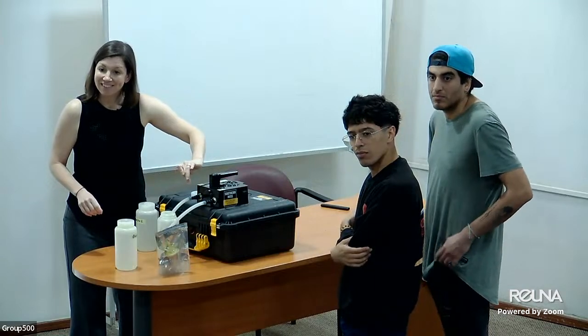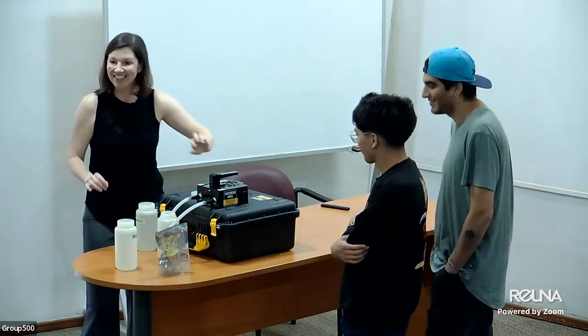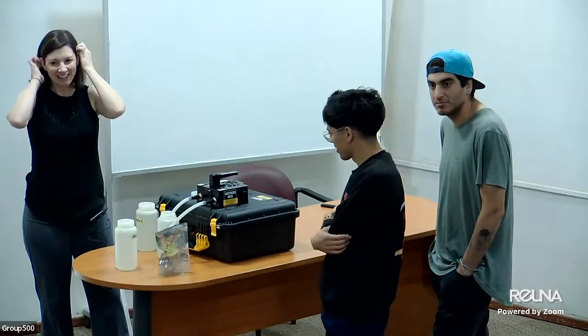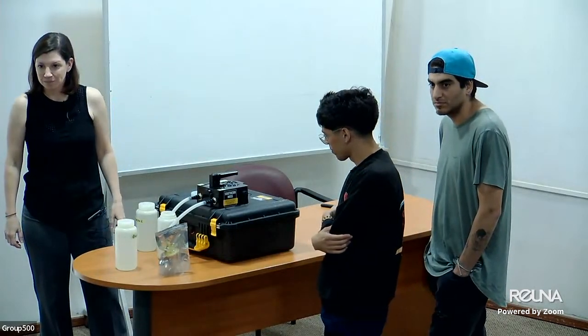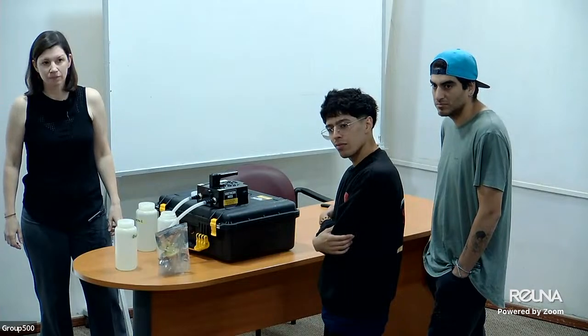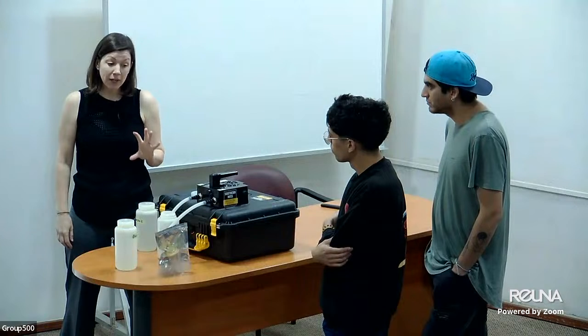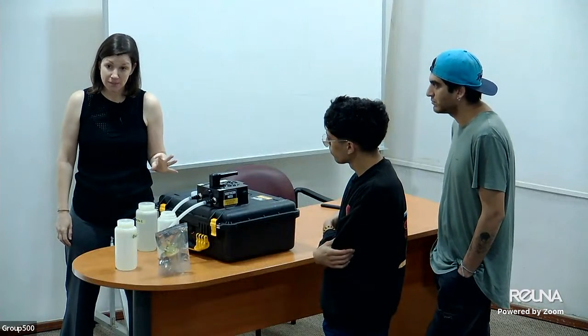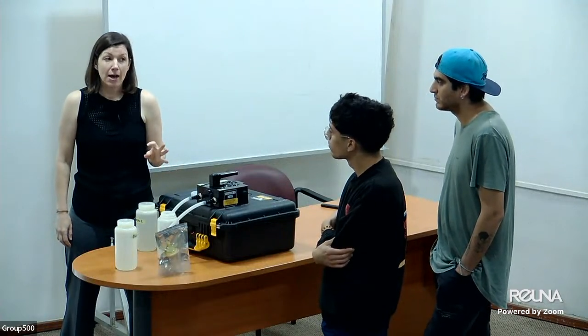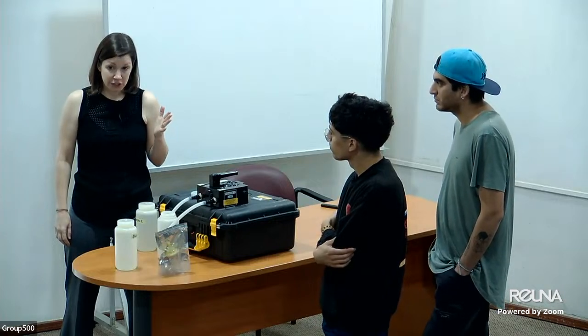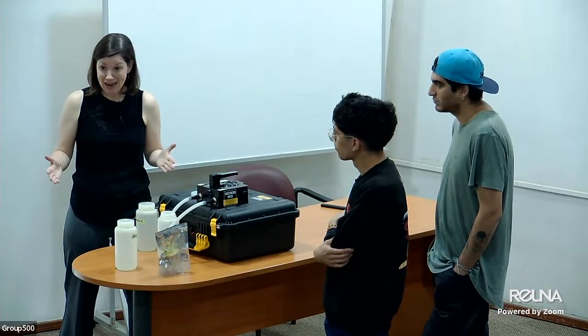I have another question. That's fine. That's why it's a workshop. What is your recommendation? Make the filter in the field, or wait to come back to the laboratory? That's a great question. What is your recommendation? So if the water is really, really clear, my recommendation is to filter on site because it's very, very quick. If the water is very turbid, it could take 6 or 7 hours.